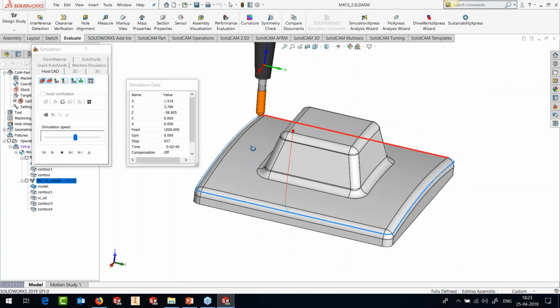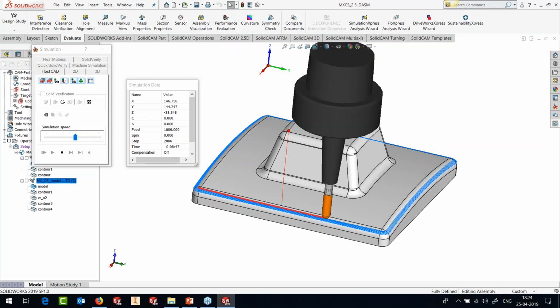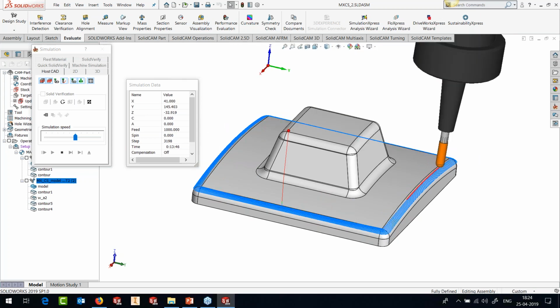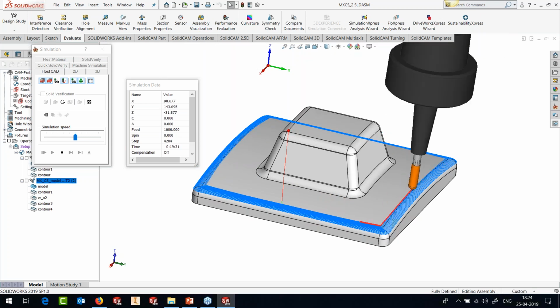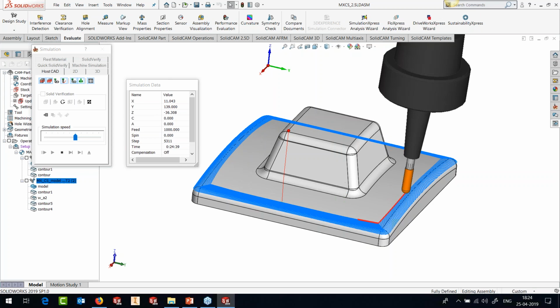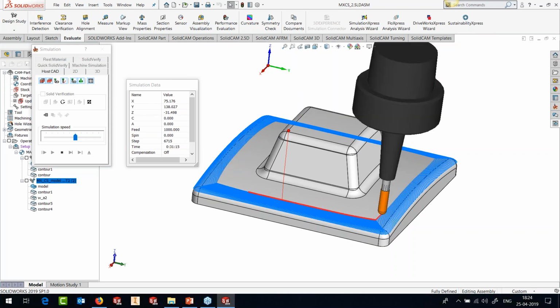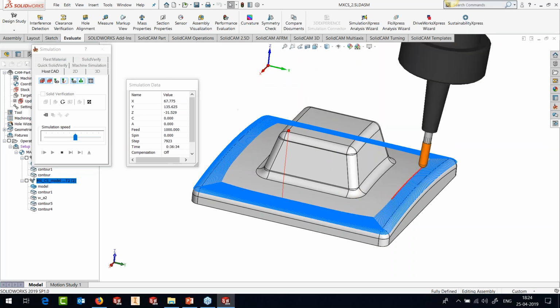You can see that it just keeps on machining, and we have used the spiral method, so there's absolutely no step over. It's great. It's gradually machining the entire mesh till the final pass is generated. So a very interesting machining strategy. You can apply it to your new paths. If you're having issues with parallel to curve, or if you want a better toolpath in parallel to curve, morph between two curves, you can use the new multi-axis constant step over toolpath engine and generate extremely good toolpaths.